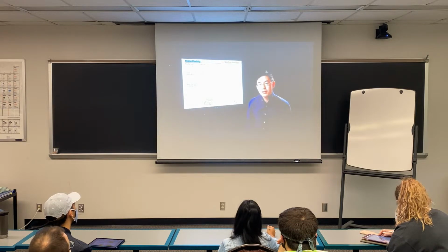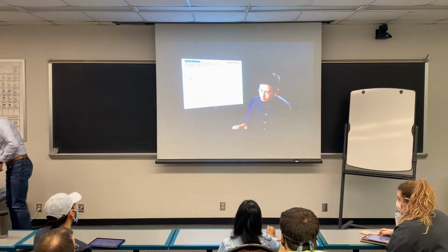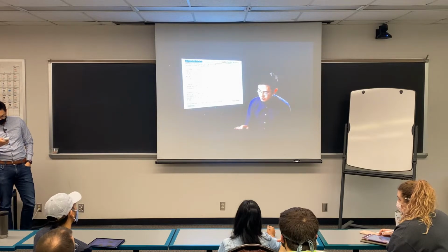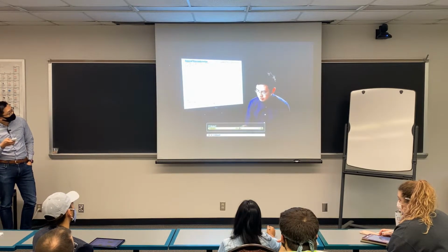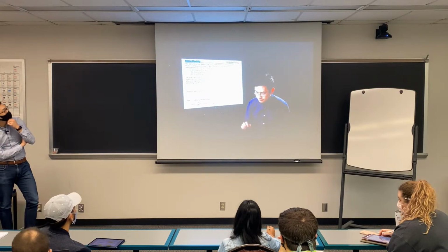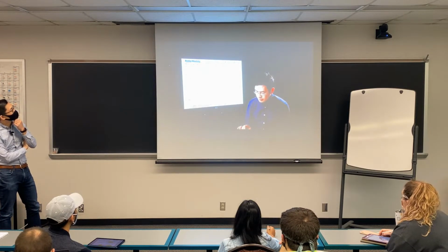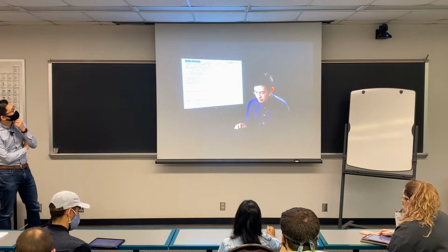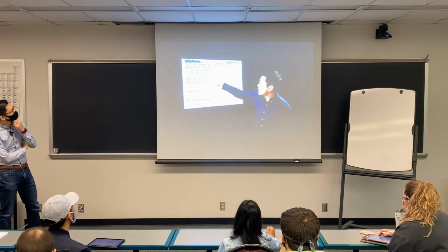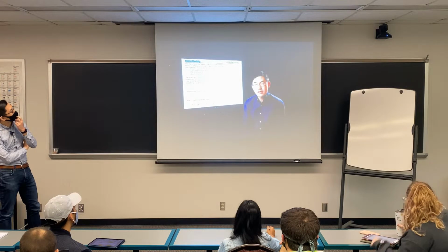Okay? So what we're going to do in today's lecture. Today's lecture is slightly different from what we talked about before. I want to go back to the slide where we talked about a few assumptions for rubber elasticity theory. We discussed that this is going to be a finite network, and the initial network is isotropic, with volume-constant driven deformation. So this first one is true at a low degree of strain.